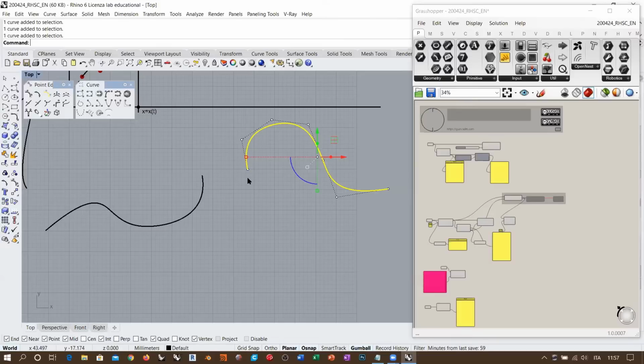Okay? Curvature is the second derivative. So it's the derivative of tangency. And so curvature expresses the variation of the tangent along the curve. Okay? As tangency defines the variation of the shape of the direction, the curvature defines the variation of the tangency. In what kind of design should you work with G3 or G4? This is very interesting because G3 and G4 also have a funny name in terms of derivatives.